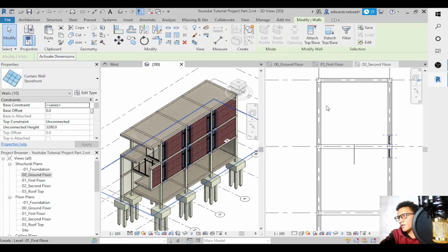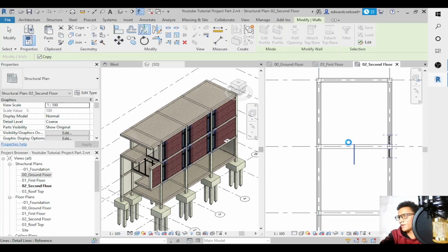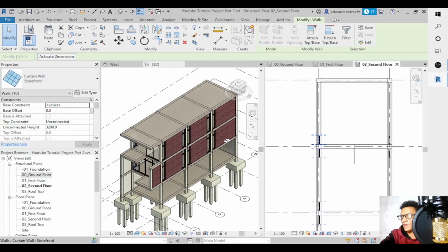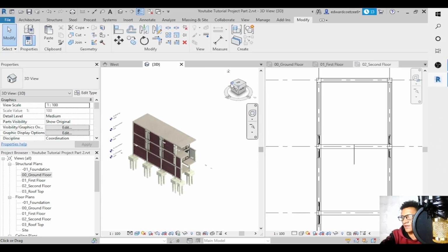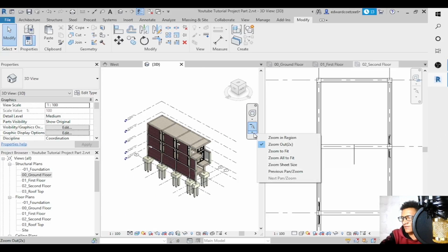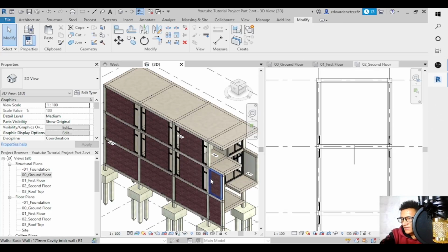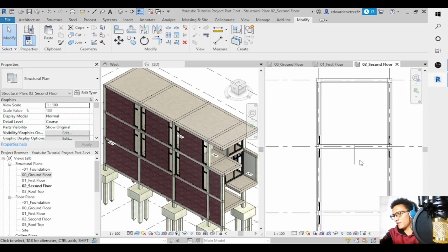And when I'm done selecting this side, I come here, click only once, and then I say mirror or MM, and then it's going to go to that side. Then I'm going to escape, check that side, and see if they all look in place. And I see they all look in place. So go to that side again of the window.